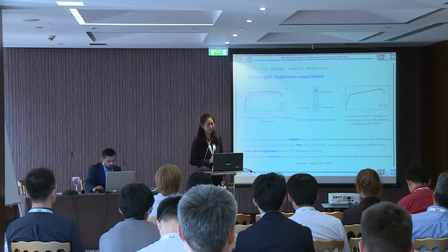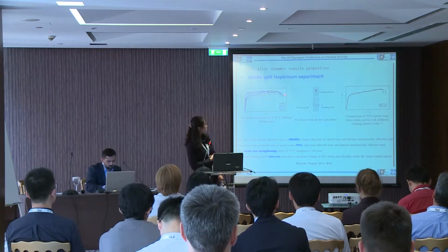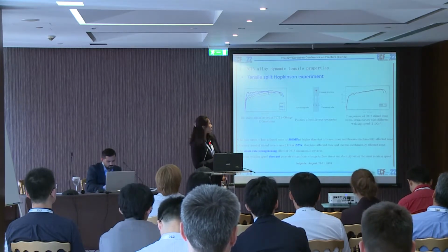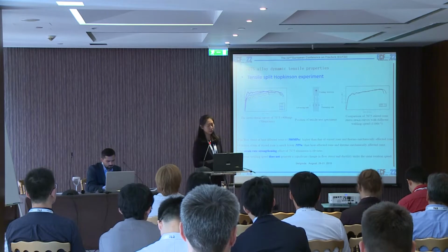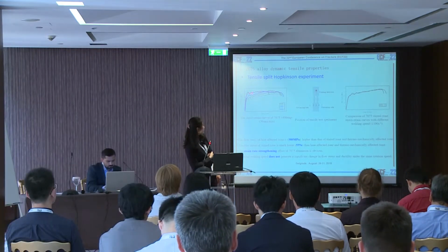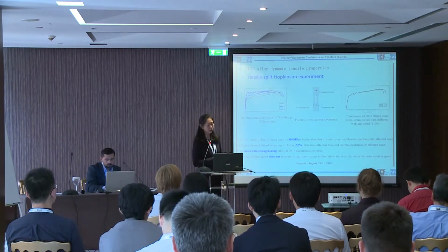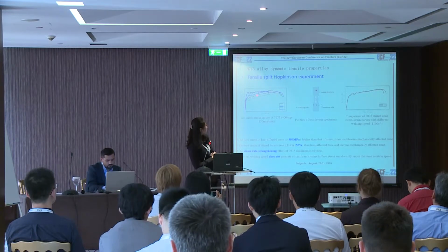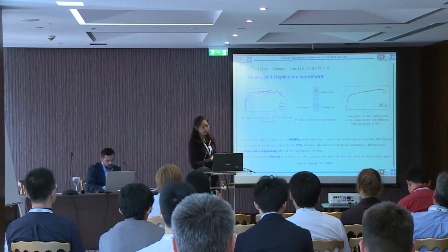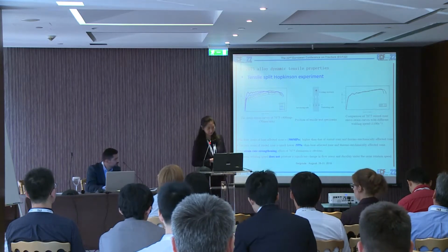This is the stress strain curves of 7075. We can see that it's similar to the 2024. The heat affected zone shows the better mechanical properties. It has the highest yield strength and peak flow stress. But what is quite different from the 2024 is the stirred zone. The stirred zone of 7075 shows the lowest ductility.